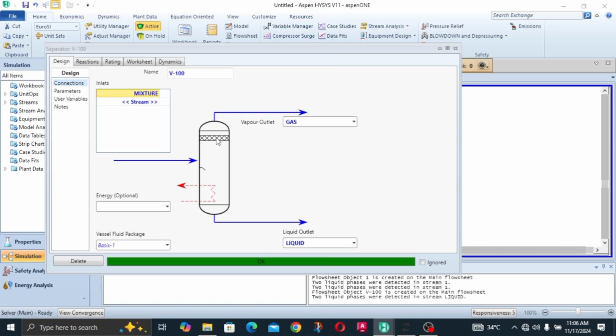And remember, in the gas outlet, we do not want any phase apart from gas, 100% gas. So the function of this padding is to trap any liquid attached to the gas, which tries to escape through the gas outlet. If there is any liquid, it just traps it. It's more like a fabric pad, I would say, or something that could actually trap moisture, that could actually trap water.